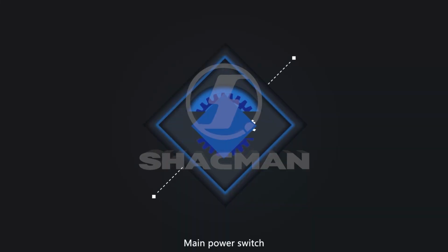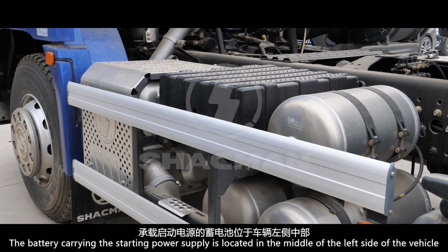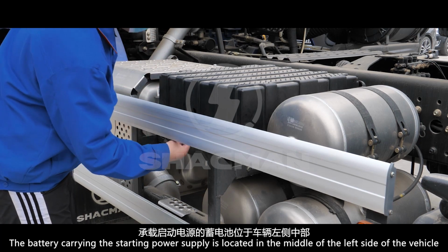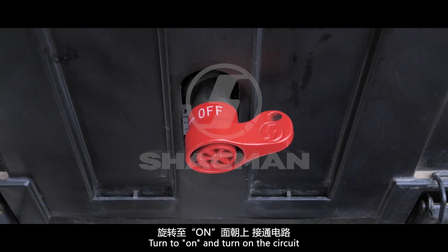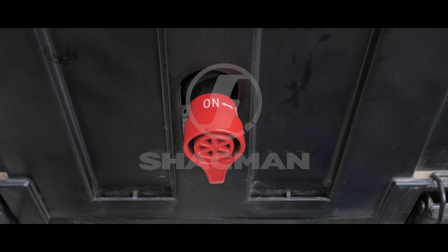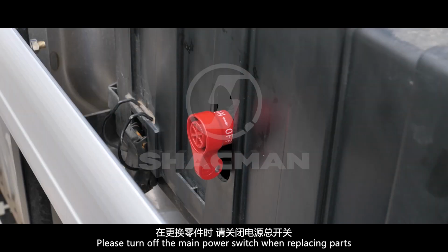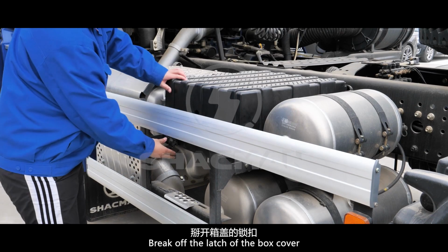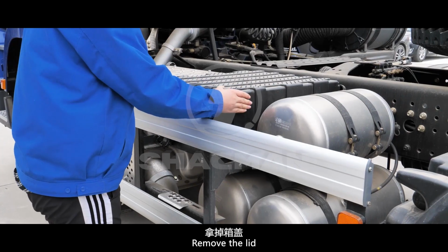Main power switch. The battery carrying the starting power supply is located in the middle of the left side of the vehicle. Insert the main power switch. Turn to on and turn on the circuit. Please turn off the main power switch when replacing parts. Break off the latch of the box cover. Remove the lid.